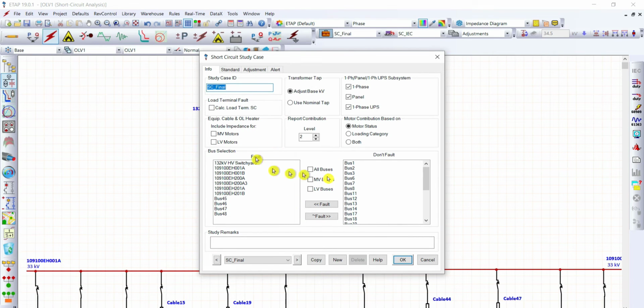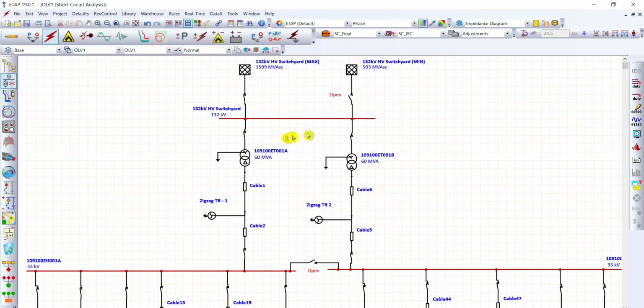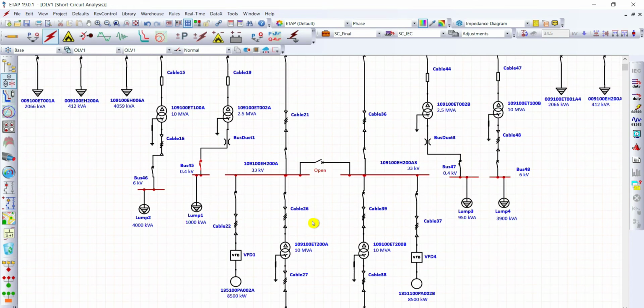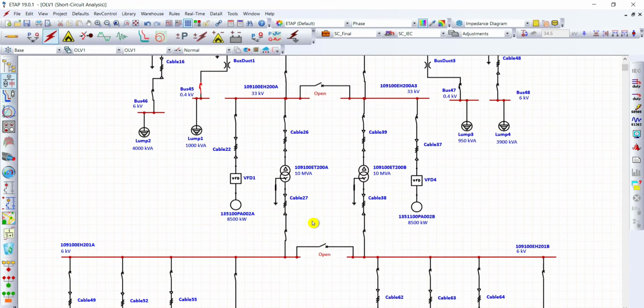Okay. So, we have here the faulted buses. Ensure that before you run any short circuit analysis, because this is a prerequisite, there should always be faulted buses. So, the red one, I'll close this one first. The red ones are the faulted buses. Once you select the short circuit button and you have already faulted the buses, the faulted buses will become red. See?